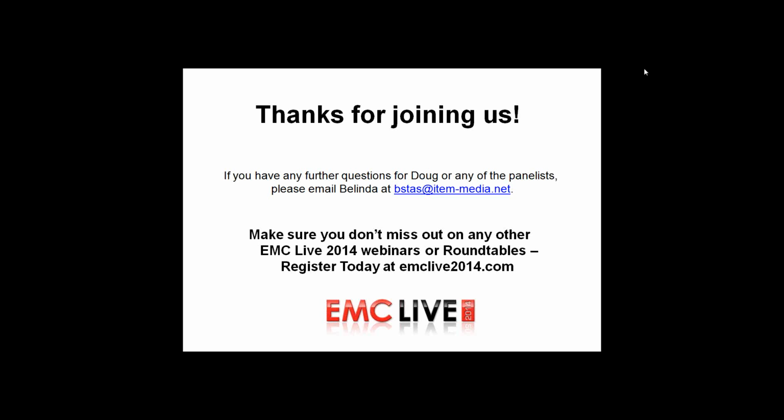Well, that's generic advice, but it applies equally to op amps as it does other circuits. Basically, you have good EMC practice, but apply it to analog circuits that you wouldn't normally think of having to do it to. Right. And I liked what you said about treating everything like it's a microwave circuit. I think always keeping the grounds near the signal so that the return is right near the signal is important as well. So same idea, but yep, I agree with that.